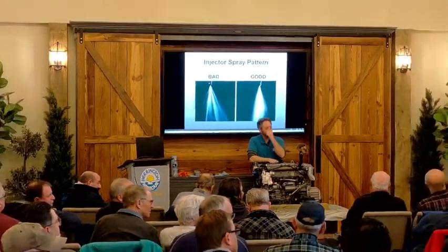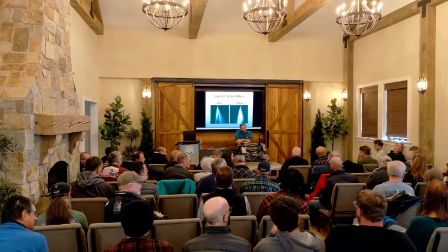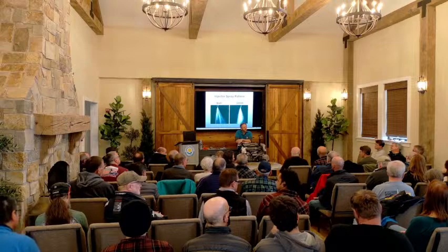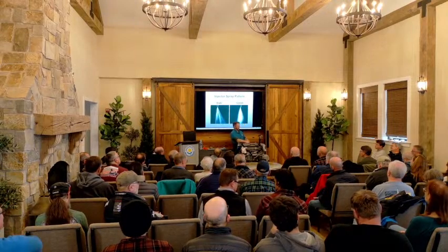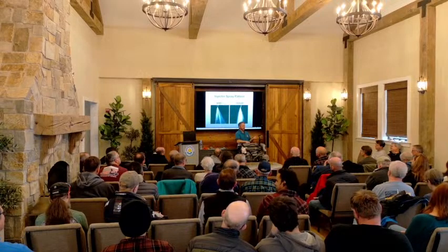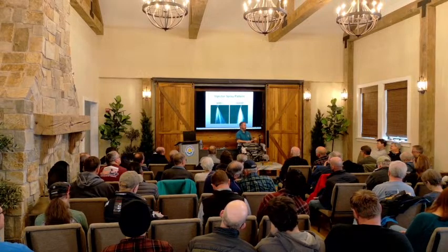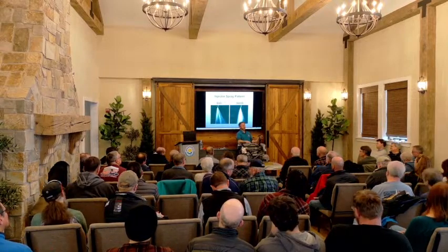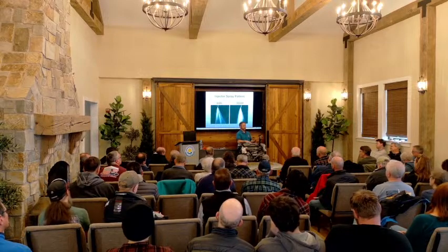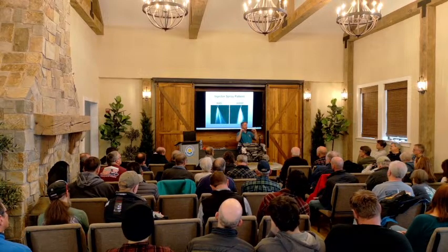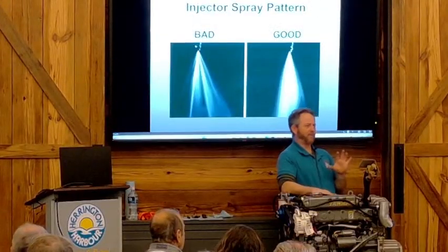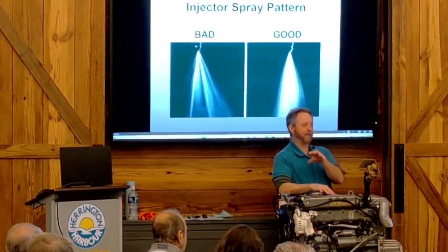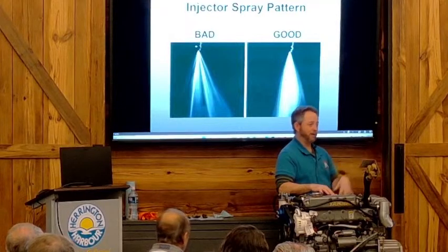Can you talk a little bit more about older engines losing compression, and how should we go about evaluating if that's an issue? Okay, so typically low compression is going to show up as hard starts, like we were talking about in the spring and fall. It's harder to start, but during the summer it starts right up. That's usually an indication that the compression is low in all the cylinders. Now, if you just have a misfire, or the engine's not running smoothly, that might be just one cylinder, where something happened in that one cylinder and the others are okay.